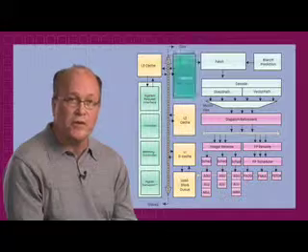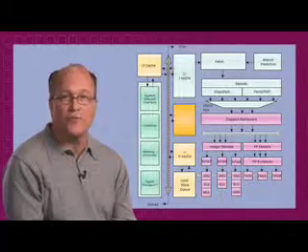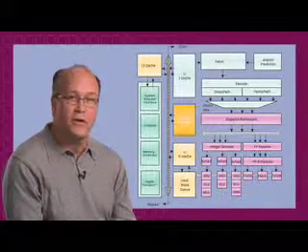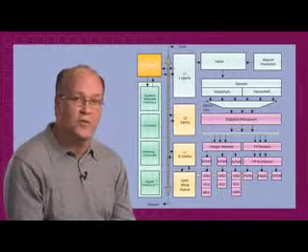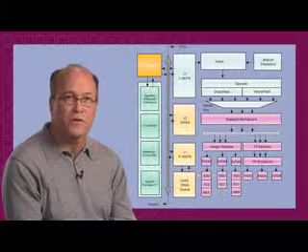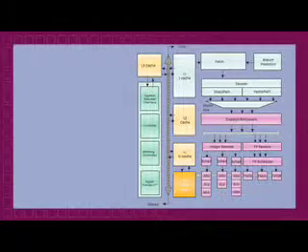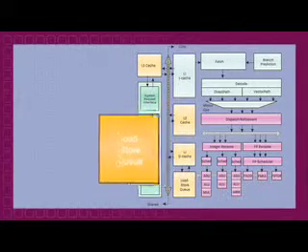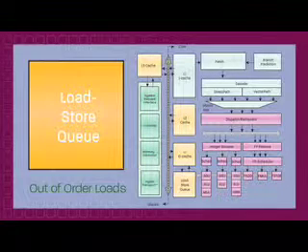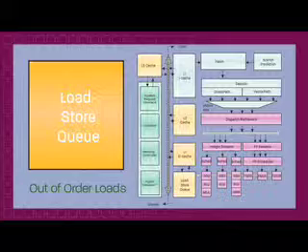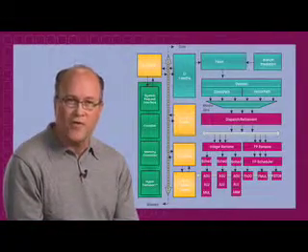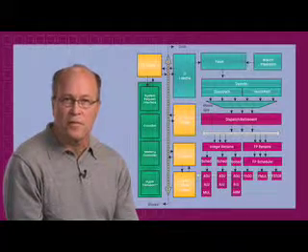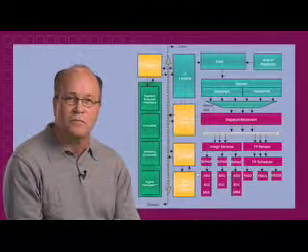Each core has 64K instruction cache, 512K L2 cache, and shared among all the cores is the new L3 cache that can go up to 6 megabytes depending on the configuration. Something you'll notice in simulations is out-of-order loads. The processor retains its in-order retirement, but loads are done out of order. This feature combined with prefetch and branch prediction can dramatically accelerate processing.